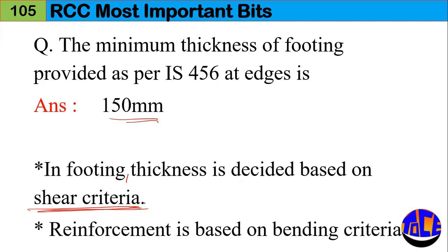Remember, the thickness is decided based on shear criteria in footings, whereas the reinforcement is based on the bending criteria.